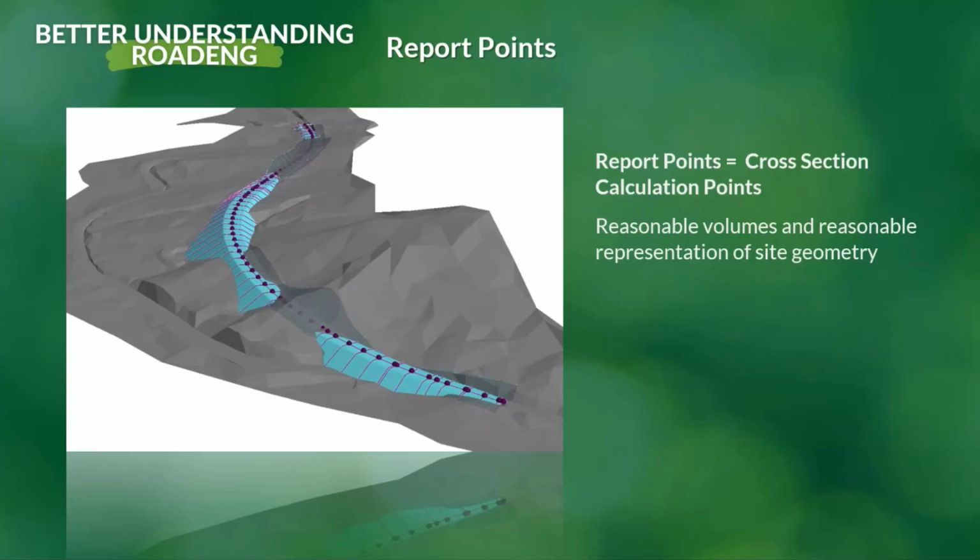For example, when you go and design a road, there is an auto interval point. These ones are used throughout your project. They have a certain distance between them, and you can configure that. When you add a curve, you get report points added for your curve geometry. When you add a culvert, you get a report point added for your culvert location. And then, of course, the final major group of report points are the standard editable report points that you add yourself.